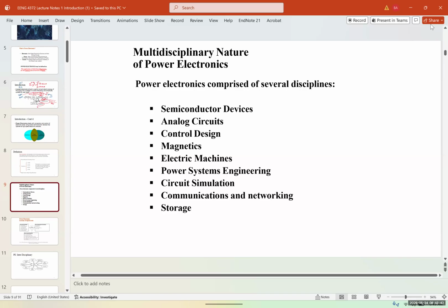So the first cars, the reason they weren't that popular is because DC motors use commutators and those wear out, so you need maintenance. That's a big problem with them. And because you can't have very high voltage, you're going to have a lot of waste in the system, heat up.